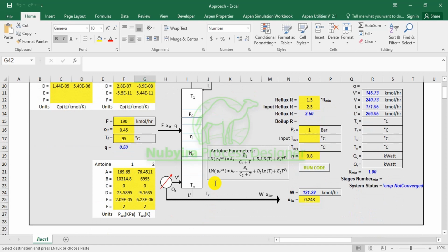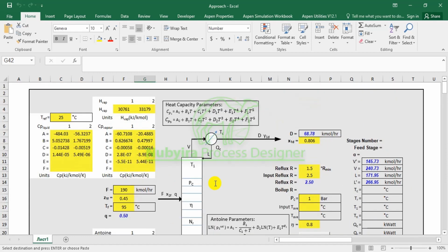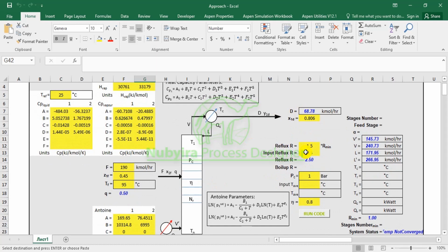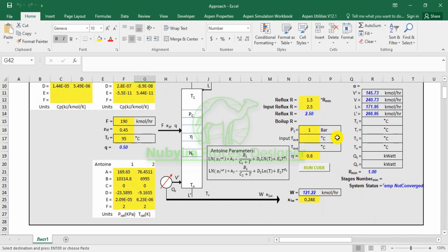And we calculated the bottoms and the distillate product flows based on the reflux ratio specified. So I'm using a placeholder for the minimum reflux ratio because my reflux ratio is based on my minimum reflux ratio. But when I was using 1.5, the reflux ratio was too low, so I was getting negative flow in my column, so I had to override the reflux ratio to be 2.5.